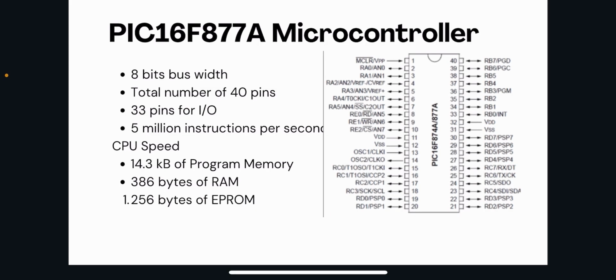The microcontroller used in our internship project is a PIC16F877A microcontroller, and the pinout diagram of it is given on the right side. It has a bus width of 8 bits and a total number of 40 pins, which we can clearly see here, and it has 33 pins for input and output.